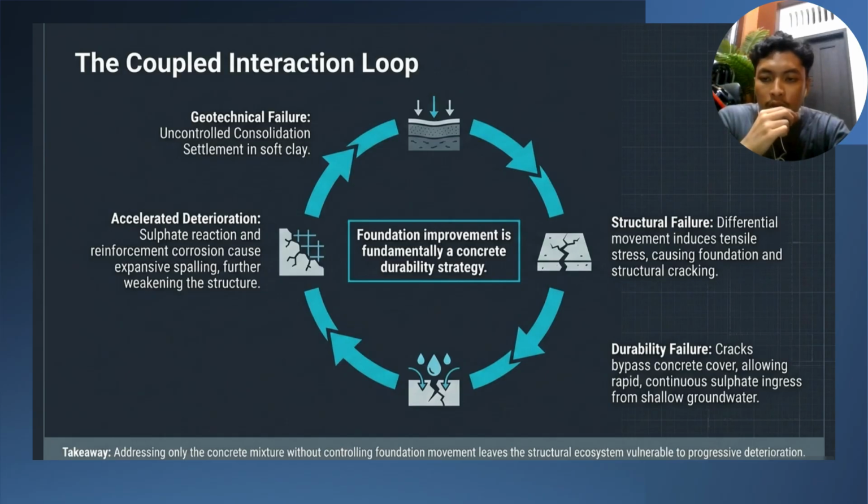Once you have structural cracks, the low permeability defense of your concrete is breached. This provides a highway for acidic, sulfate-rich groundwater to reach the reinforcement.